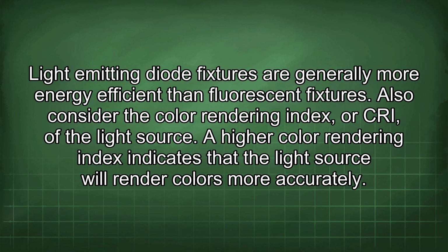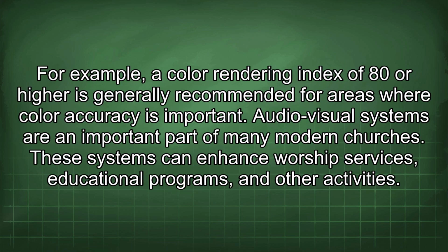Also consider the color rendering index, or CRI, of the light source. A higher color rendering index indicates that the light source will render colors more accurately. For example, a color rendering index of 80 or higher is generally recommended for areas where color accuracy is important.